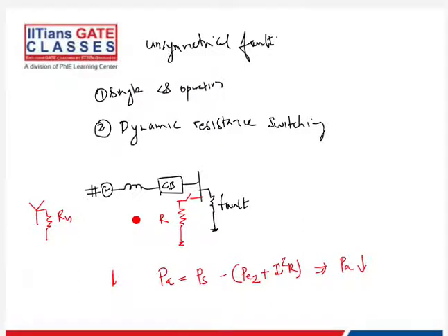So there is a thumb rule whether to choose resistance grounding or reactance grounding, right? For the generator, X0 by X1, that is zero sequence impedance divided by positive sequence impedance.